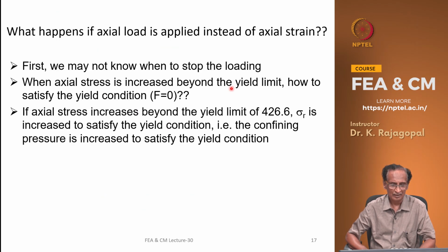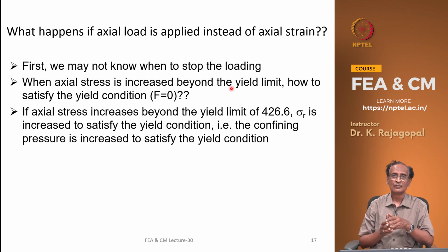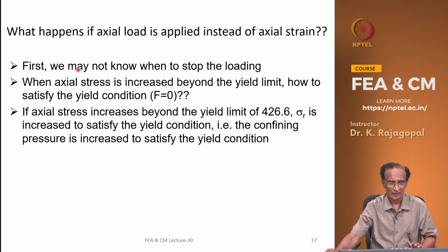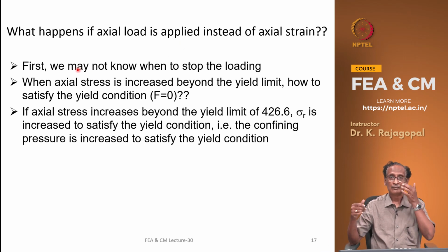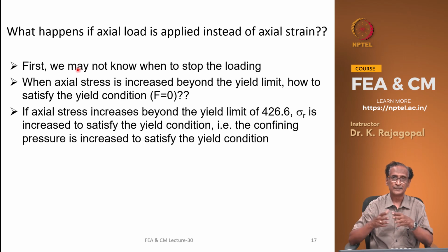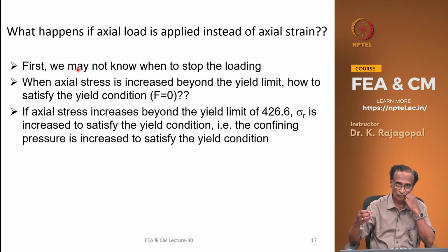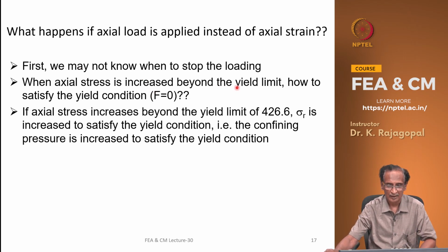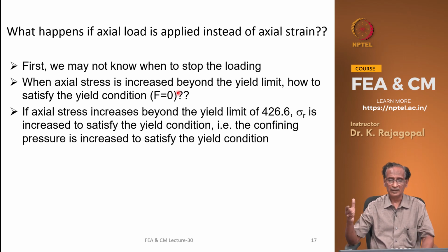And let us say instead of applying axial strain, we apply axial forces. What happens? See, if we want to apply load, first of all we do not know how much load we need to apply, because in some cases, let us say you have a bearing capacity of a layered soil, we do not know what is the maximum pressure that the soil or the footing can take, and in that case we do not know what pressure we need to apply. And let us say we go on increasing the axial stress, and at some point we apply a stress more than the yield limit,